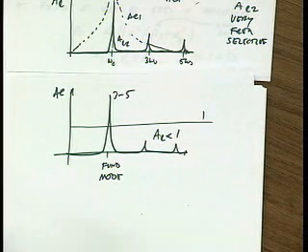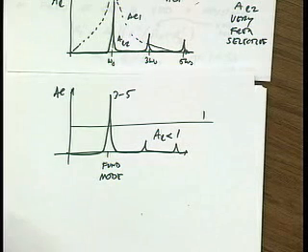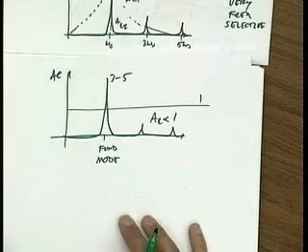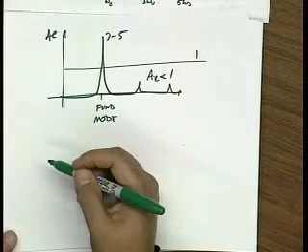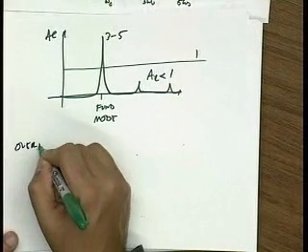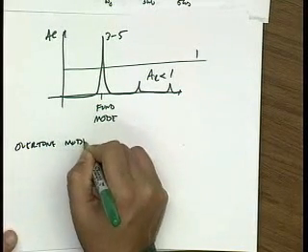And because the feedback factor, the loop gain, is so frequency selective, this will also have very good frequency stability. It will not oscillate at any frequency except the frequency that it likes to oscillate at. And so it has a good noise rejection. Now you can see how you might design an overtone mode oscillator.